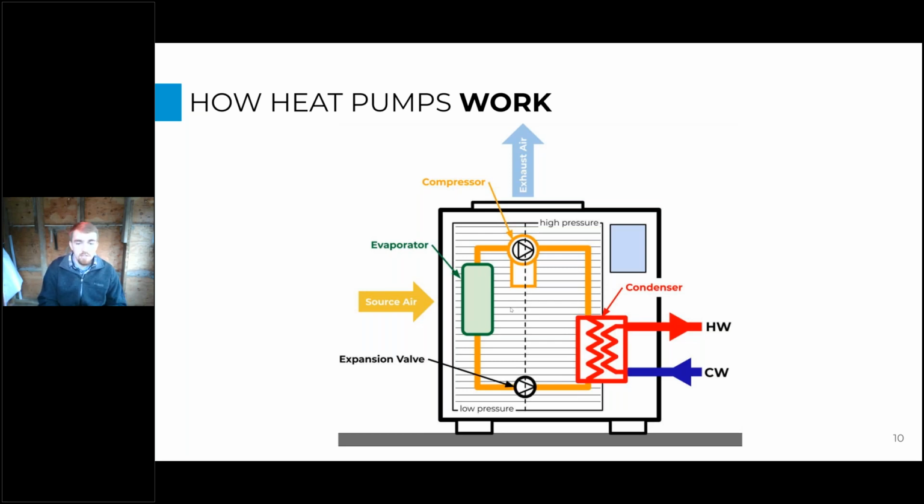And as you decrease the pressure, you're decreasing the temperature because of what's happening on the atomic level in that gas. You might have seen this before if you're spraying your keyboard with dust off, right? If you hold that trigger down and most of that gas comes out, now your can is actually freezing cold. That's because the pressure inside that can has dropped significantly and quickly, so the gas that's remaining in that can has also dropped in temperature really significantly. The same thing happens when you pressurize that can. It's actually going to get really warm.